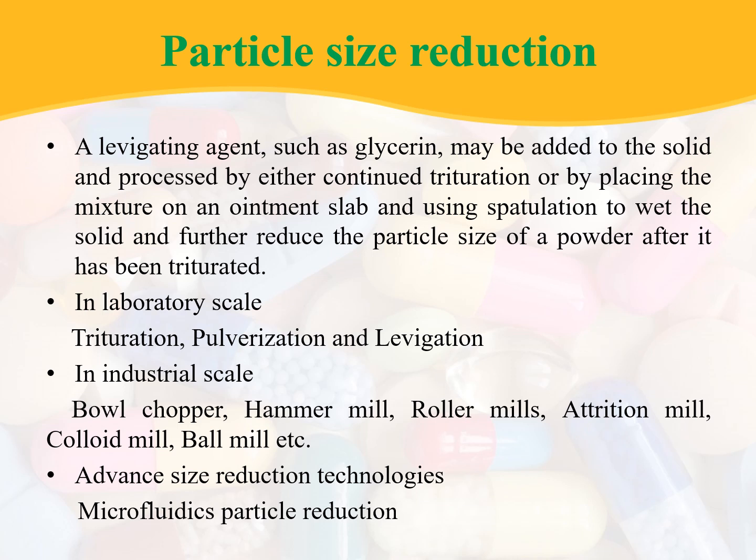In laboratory scale, trituration, pulverization and levigation are used for particle size reduction. Whereas in industrial scale, bowl chopper, hammer mill, roller mills, attrition mill, colloid mill, ball mill, advanced size reduction technologies and microfluidics particle reduction are employed.